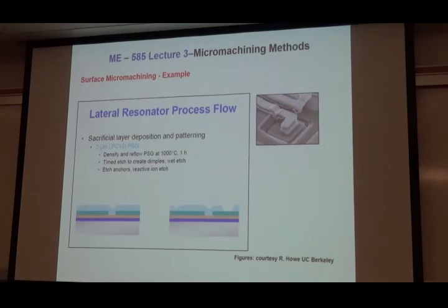Okay. So it looks like in that single photolithography process, you do the dimple and the anchor? No, dimple first, then anchor. Oh, two separate. I'll just keep my wafer out. Okay. So I was wondering how you got one deeper than the other. Yeah, so it's essentially two. Okay. And then we're going to do this again with the four-layer polymer process, right? But I just want to give you a brief introduction right now. So, everybody with me on this?